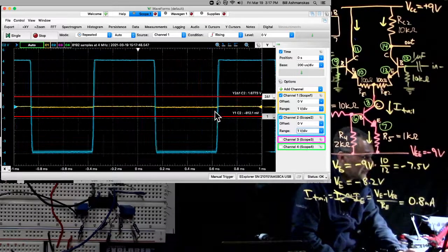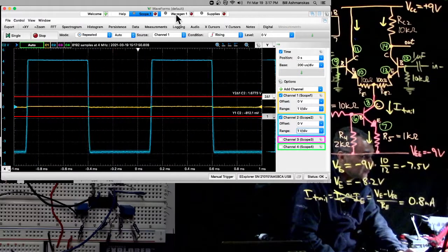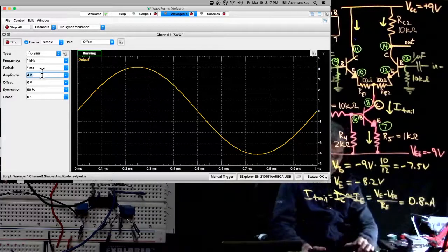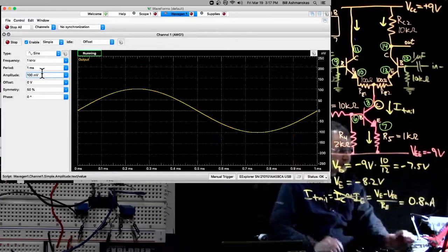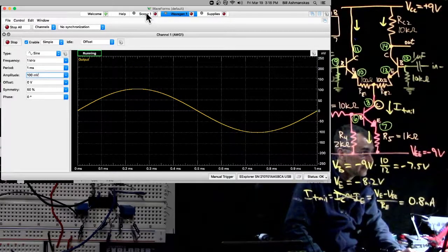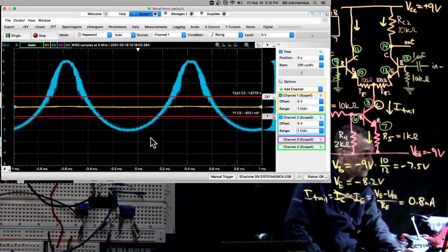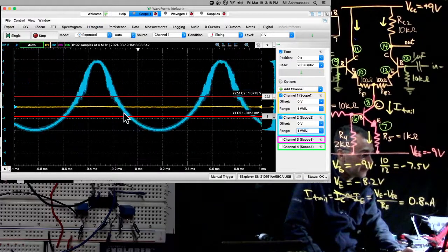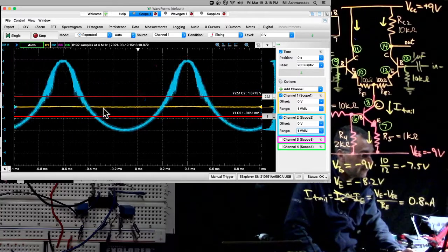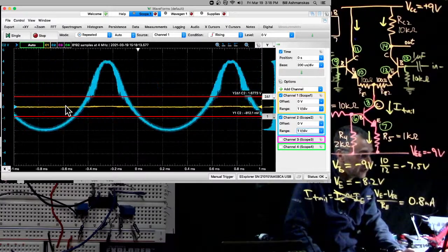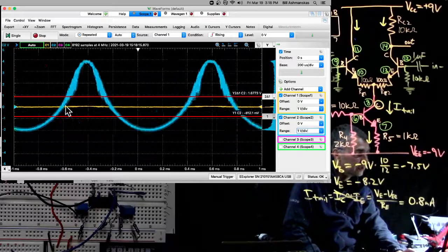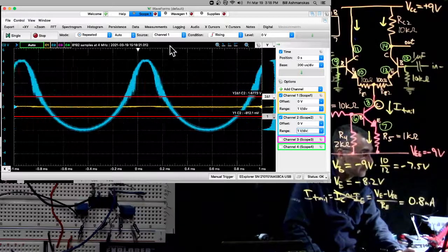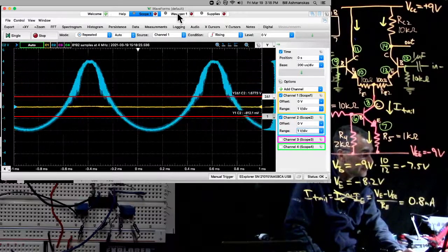It's still too big. So now let's go back over to WaveGen here. And instead of, oh, that's huge. It's a 4-volt amplitude. So let's try a 0.1 volt amplitude. And we go back over here. Oh, I think it's so big we get kind of a nonlinear response. So anyway, it seems like that's like 6 volts peak to peak compared with 0.2 volts peak to peak. That's about right, I guess. Let's try to make it a little smaller so it's not so nonlinear in the response.